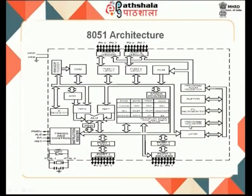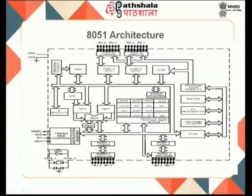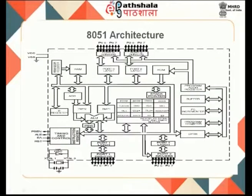And we have special registers, where I can call this DPTR, which interfaces the memory address for the external memory. Sometimes we will not use only the RAM and ROM; if this is not sufficient, we will use external memory. That particular external memory is accessed through this DPTR. The memory address will be sent through this DPTR, because the DPTR has a 16 bit address, so 2 registers are combined together. So, a 16 bit address will be sent through this, where we have a program counter.